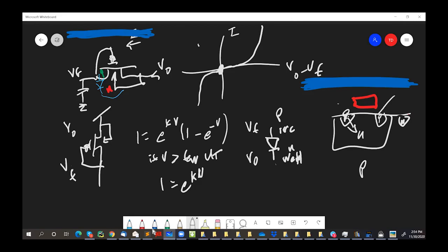But with this structure, if you cover it with metal so that no light shines directly on it, this junction won't get affected by parasitic photocurrent because it's surrounded by that N well. And so you can blast light onto the surroundings, like on a surrounding photodiode, and it won't affect the resistance of this switch. It's certainly not true of any switch that you make out of a normal NFET.